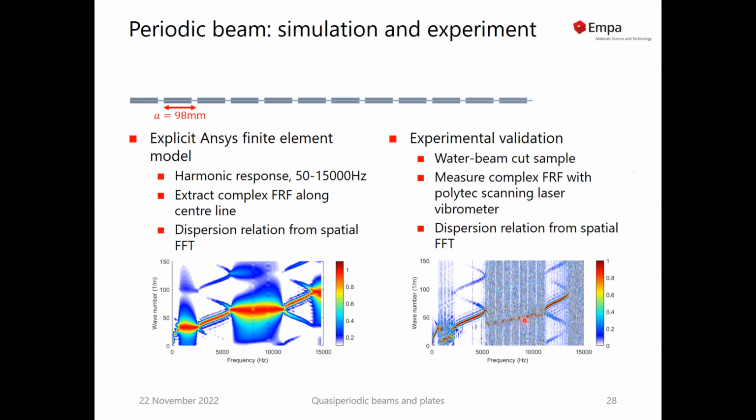What we also see is there is some energy leakage in the band gaps to other wave modes. If the energy cannot propagate as a bending wave in this direction, it tries to propagate in another way. This here is a dispersion relationship of bending waves in the out of plane direction, according to this graph here. So there is still some wave propagation visible, but in this noisy area, you clearly see the presence of a band gap.